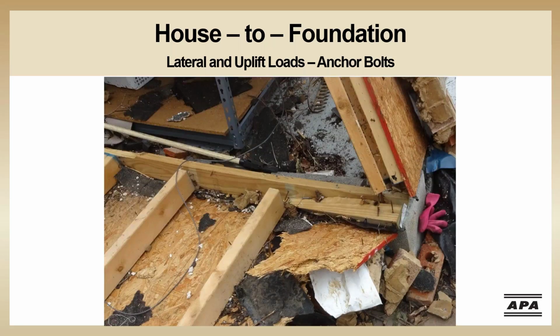The code also specifies that a washer must be included on each anchor bolt. The washer is a critical piece of the assembly because it provides the surface area against which the sill plate bears when the wall is experiencing an uplift load. The lack of a washer or the use of a smaller washer can cause the sill plate to split or to be pulled up over the anchor bolt, as can be seen in this photo.